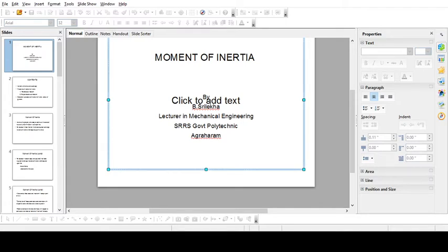then the moment of inertia of this section about the zz axis is simply Izz equal to Ixx plus Iyy. In this case, you can take x as the distance of the piece from the y axis, y as the distance of the area from the x axis, and r as the distance of the area from the z axis.